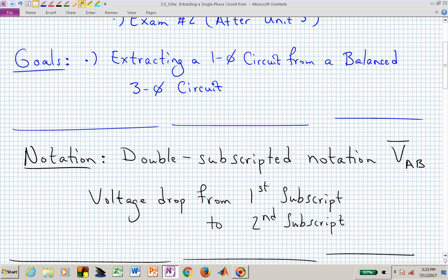Let's just remind ourselves of the notation that we are using. We're using a double subscripted notation, and if I now say V sub AB, that's meaning the voltage drop from the first subscript, which in this case is A, to the second subscript, which in this case is B. So if I had two terminals, A and B, and I say V sub AB, then I'm interested in the voltage dropped from terminal A to terminal B, or if I had a multimeter, I would take the negative lead and set it on B, the positive lead and set it on terminal A, and measure that potential difference between